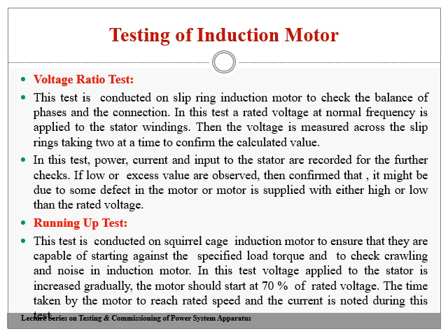If it is according to design condition, then we say that the rotor is perfectly designed, or the induction motor has passed the complete voltage ratio test. Otherwise, if it gives a different value other than the specified value or nameplate details, that has to be brought to the notice of the manufacturer. That's about the voltage ratio test.